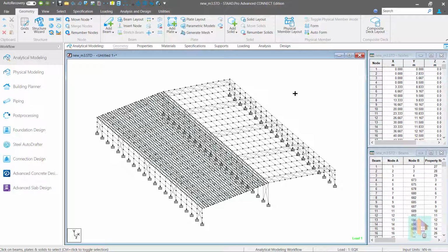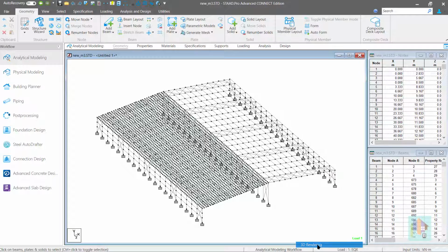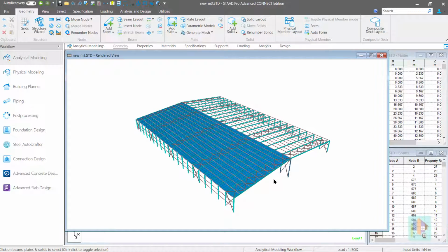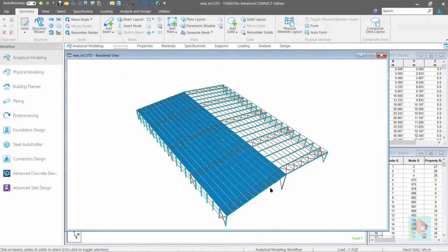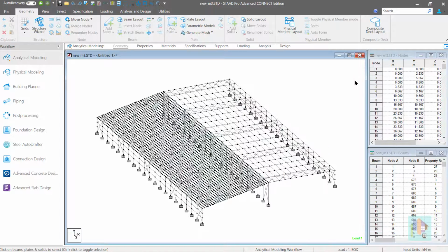But if we model the roof, it increases the modeling and analysis time. For any second order or iterative analysis like section selection, finite element roof is not efficient. So we normally skip modeling the roof and apply the dead load directly on the supporting members which carry and transfer the load, like purlin and rafter. I have already discussed this in part 1.1. You can check that for more details.